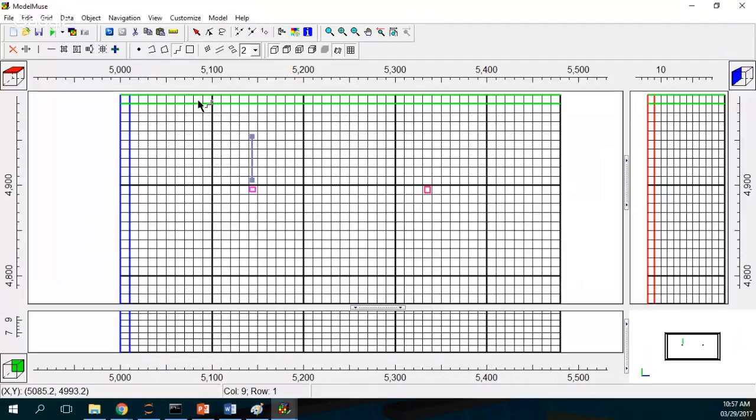Okay, I have two options. Whether I create one object per drain, so in the end I will end up with 16 objects, or I do composite objects, what is called polyline sections. I would prefer to use polyline sections because it's less work. All the drains will be defined by the same object, so I can apply different conductance, different parameters, to the whole set of drains. Okay, so it's my option.